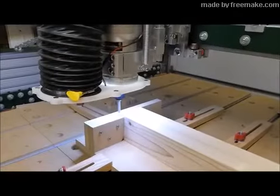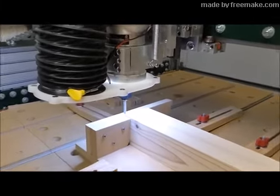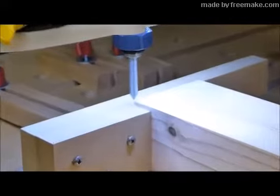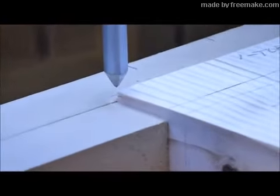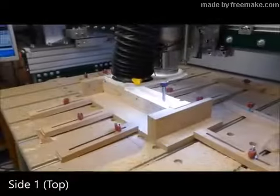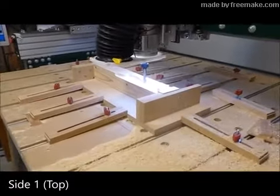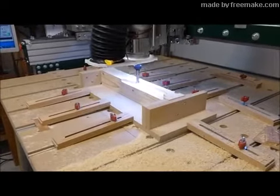Here is a centering bit showing the 0 point of the work coordinate system. The 0 point for the work coordinate system for each face's toolpath is the top left front corner. The Z0 is actually the top of the stock. This way the machine does not have to be re-zeroed for each turn of the stock. Now back to the original cutting of the top face of the stock.